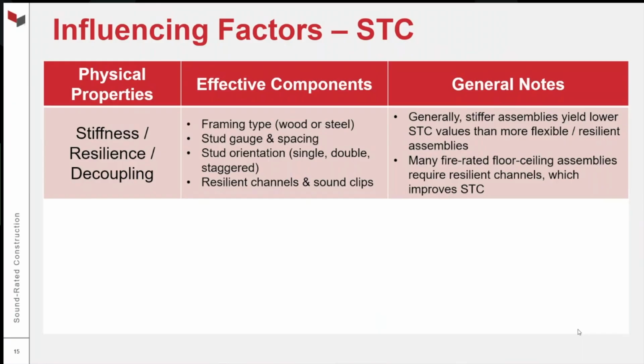But what I will say, as noted on the right, generally speaking, assemblies with stiff framing conditions will yield lower STC than more flexible or resilient framing. And that's especially true in single stud walls that don't have resilient channels or sound clips or something else to add some resilience to that wall. For fire-rated floor ceiling assemblies, many already require resilient channels to achieve the fire rating, and resilient channels are great for STC. I'll talk about that more later.